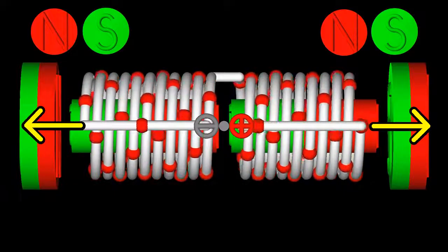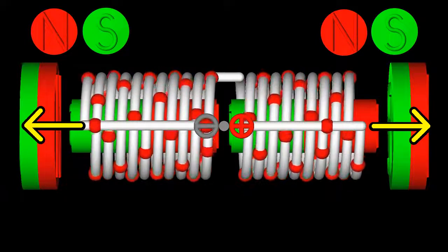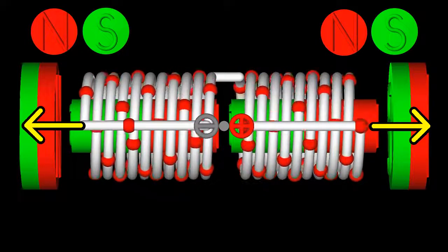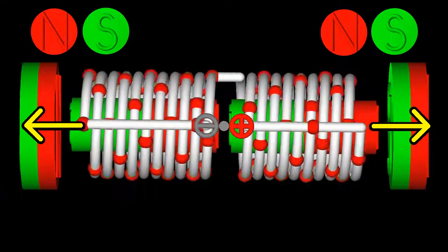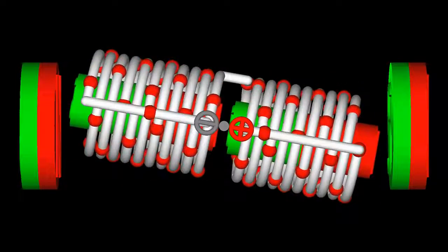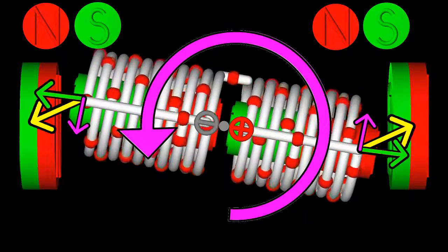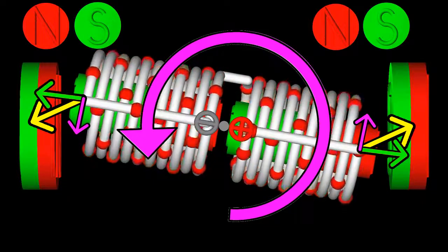Now, attractive forces are acting between the electromagnet and the permanent magnets. Both vectors are pointing along the center line, thus no torque is produced. Whenever the electromagnet is deflected, the produced torque points back to that stable rest position.